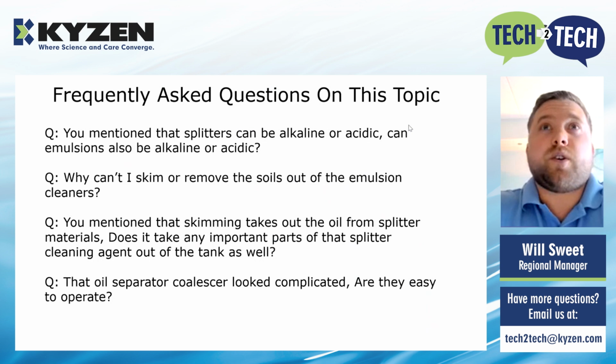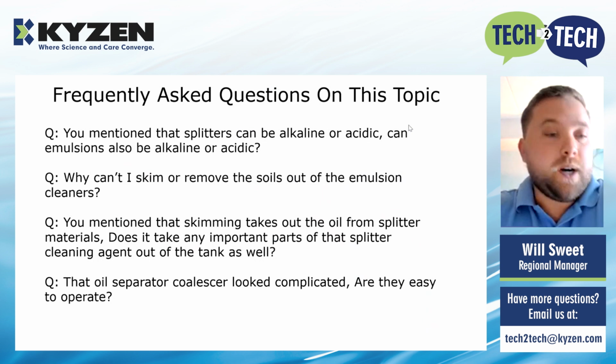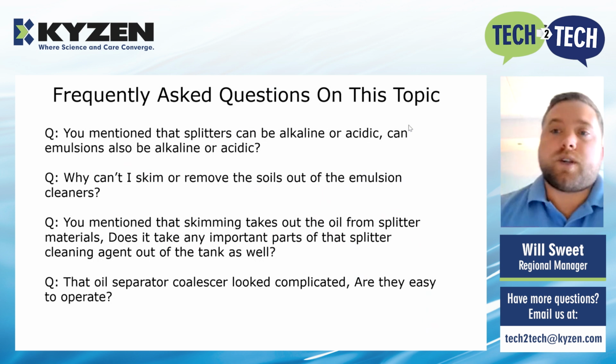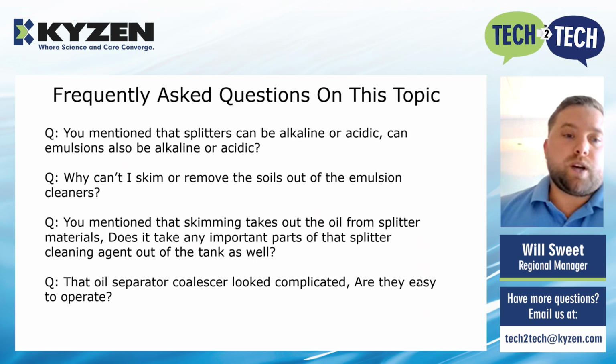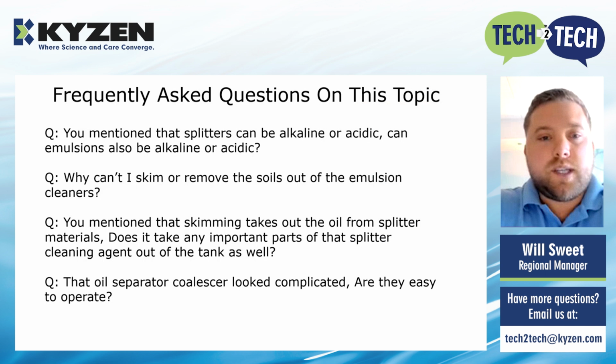Other things, you can also lower the temperature. So the best time to run a coalescer is when all the shifts are over, and maybe you have a couple hours of downtime, so the entire bath can cool down and slow down, and then the oil will separate quicker. But that is really the only thing you're worried about when running a coalescer. And that is all I have for today.